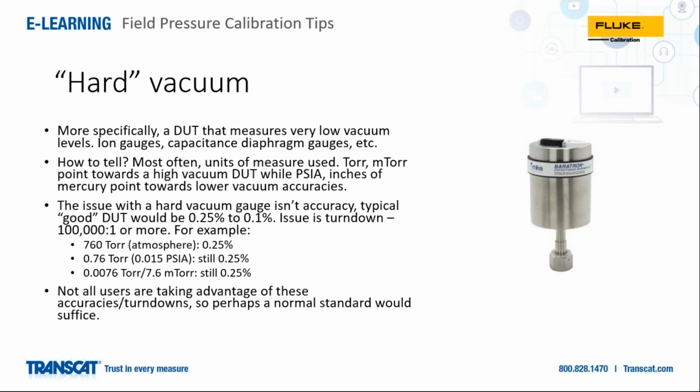And they had a few of these gauges that they're using to basically determine whether the lid on the crucible, the cradle, or the pot that they melt the steel in is open or closed, and they melt the stuff under vacuum. The only reason they were using these gauges is that they had a 4 to 20 milliamp loop output, so they could read it remotely. As far as operation goes, they didn't really care exactly how good the vacuum was down at the bottom. They just wanted to make sure it was mostly vacuum. So they were using these equivalent to, you know, a little steam gauge that measures 30 inches of mercury.